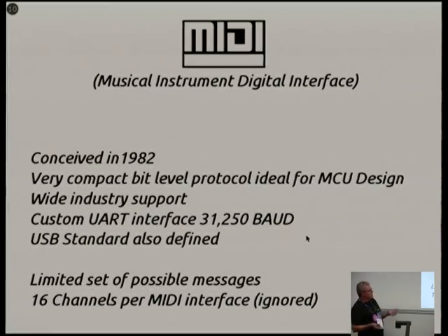So MIDI was designed really to capture and play back musical instrument notes and pedals and that kind of thing. Not originally designed purely as a control interface. Very, very compact. Everything is bit level. So a note off signal is 3 bytes, and the first 4 bits indicate the command itself. The next 4 is the channel. So it's very, very low level.